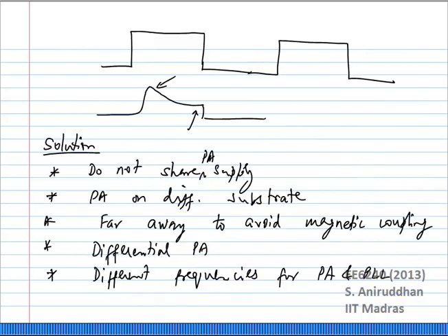Specifically, we were interested in the PLL system, because the PLL itself does not turn on and turn off because its transients are very slow. What happens is, when you don't turn off the PLL but you try switching the PA on and off, the PA, being a high power system, will shift the output of the PLL ever so slightly. And when this happens, you will see a frequency or a phase error, and you will see some settling time, and you will see some behavior like this for the EVM.